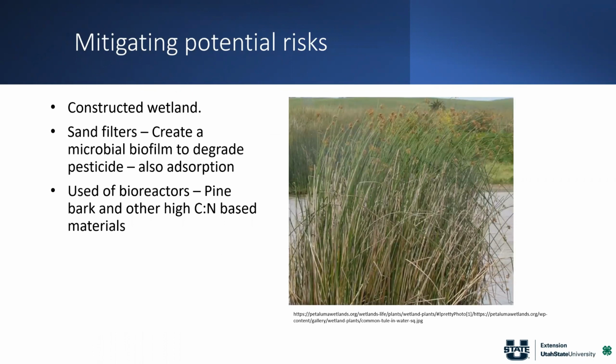Also, as I told, we can have a constructed wetland before we collect the water to the retention pond. Or if you do not have that retention pond, you can have a constructed wetland with a lot of different plants, and those plants will clear out the pesticide, and then you dump that water to the drain or river or wherever it goes to the wetland.